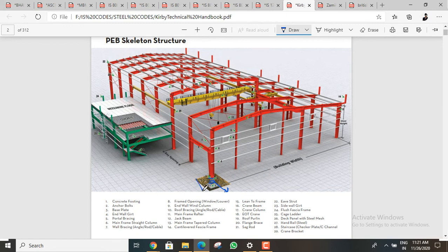The total below the structure, below this flooring, will be the civil engineer work. Come to the above, we can have the mechanical engineer as well as the civil engineer do the work of this PEB. So come to here, this will be the column, and this will be the rafter. And here this is also a column, and these are the gable columns for resisting the wind force. This will be the main middle column.